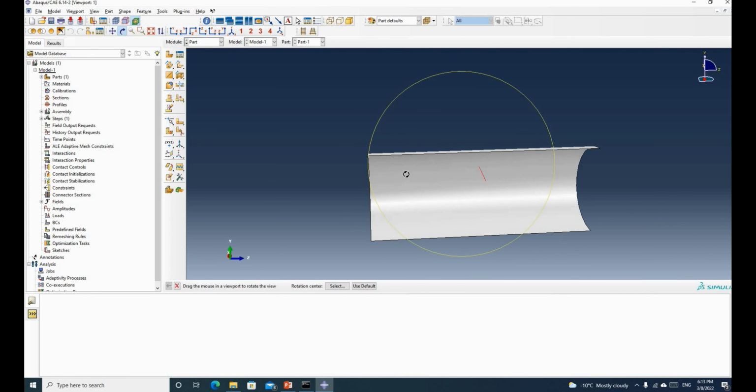And next part. Since we are going to perform a buckling analysis, we need to introduce some imperfection, because in ABAQUS, the geometry is perfect. We don't have any cavity inside, and the material model is perfect. However, in reality, we always have some imperfections, like slight changes of dimensions, or some flaws inside the material.